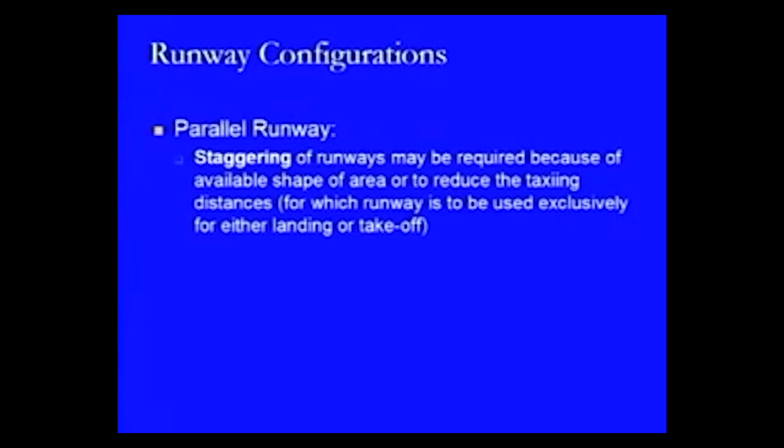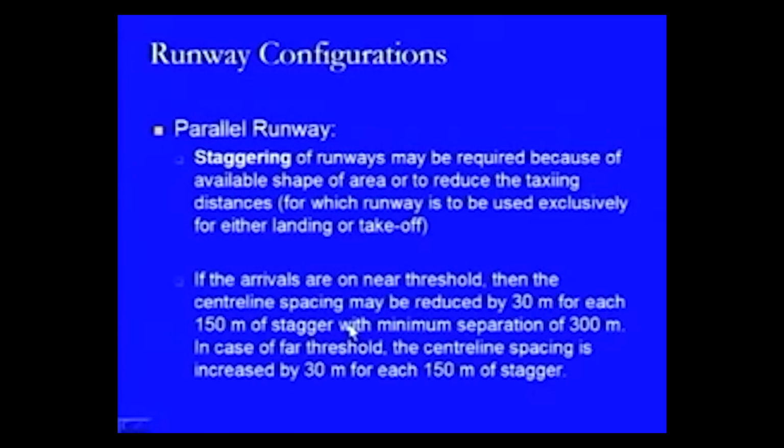Then staggering of runways is also required some of the times, because the available shape of the area is such, or at times we are interested in reducing the taxiing distance, that is the distance by which the aircraft is coming away from the runway towards the apron area. That is the case why we go for the staggering conditions.